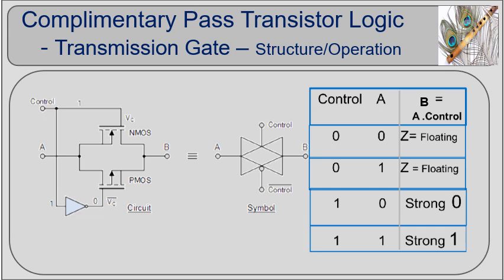A transmission gate with a logical low control signal is switched OFF and is driven into a high impedance or floating state of operation. With a logical high control signal, the FET conducts and transfers the input signal to the output. In complementary mode of operation, both logical low and high signals are efficiently passed on to the output. Complementary pass transistor logic is popular for low power applications and offers advantages over PTL like full voltage swing, bidirectional signal flow, and high speed operation.